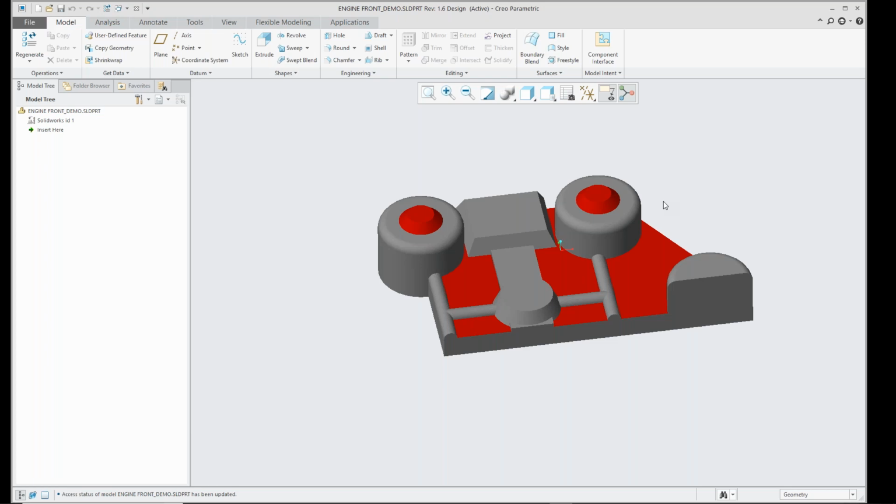So just like the collaborative design that we use with Creo directly between the individual files inside of multiple Creo sessions, we have that same ability between Creo and SolidWorks. So we have the ability to once again do real-time collaborative design between multiple CAD systems. So that's where this comes in and is very beneficial. As I said, starting with Creo 4, the Unite technology allows you to open up native files from other software, and have them recognized as the actual native file and not converted into a dumb solid.